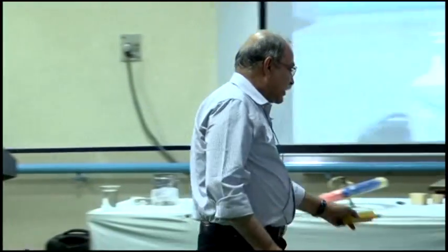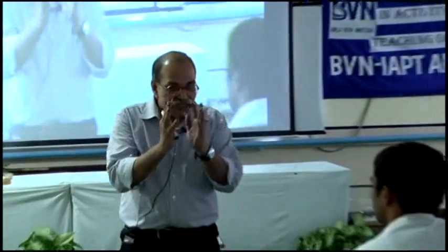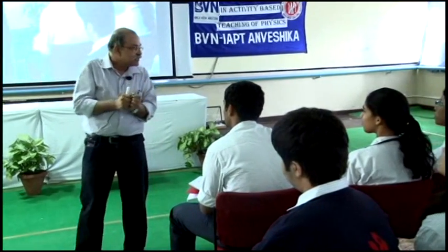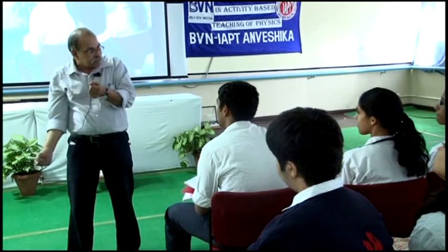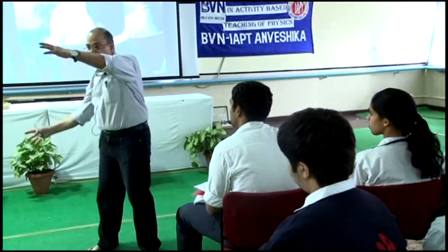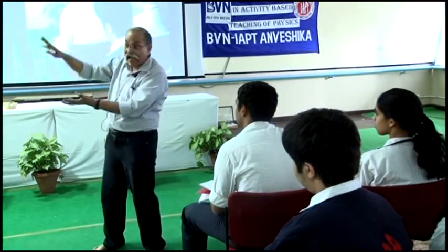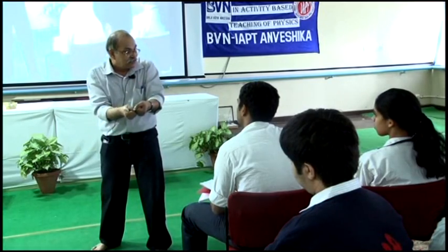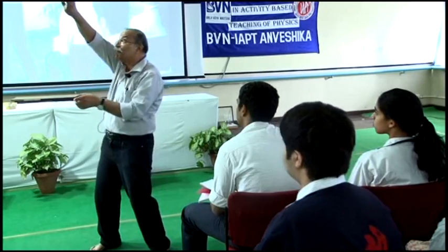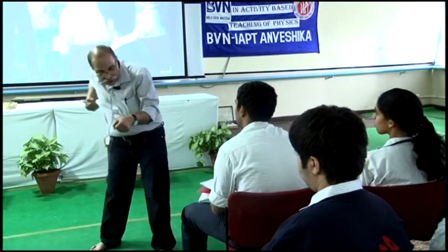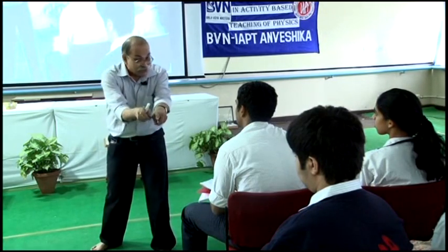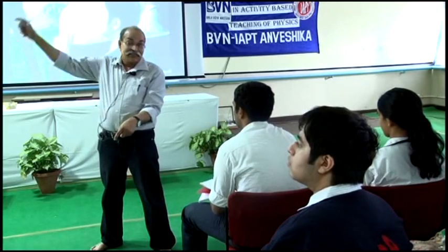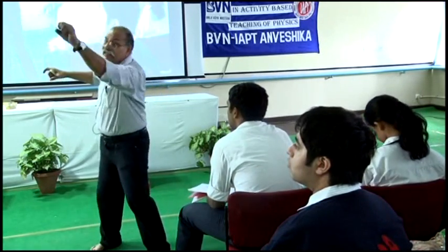There is another way which you can understand qualitatively. If the hinge is not there, or hinge is there but it is not exerting proper forces, some screw has gone loose, then because of this mg, the door will try to turn. From this side it will try to turn clockwise. As it turns clockwise, it will push the lower portion of the wall or lower portion of the hinge with much greater force inside. See, it is rotating this way, and this is coming out, and this is going in. So it is going to push that wall, the lower one, and therefore the wall should push it in the forward direction. That is the direction of F4. The other part of the door is coming out, and the hinge is saying no, don't go.